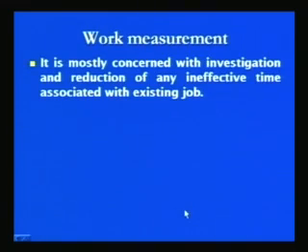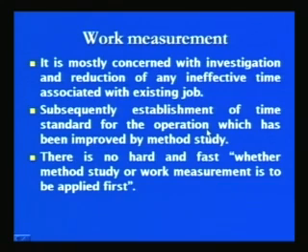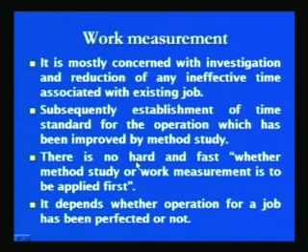On the other hand, work measurement is mostly concerned with the investigation and reduction of ineffective time associated with the existing job, and subsequently the establishment of the time standard for the operation which has been improved by the method study. There is no hard and fast rule whether the method study or the work measurement is to be carried out first. It depends whether the operation for a job has been perfected or not.